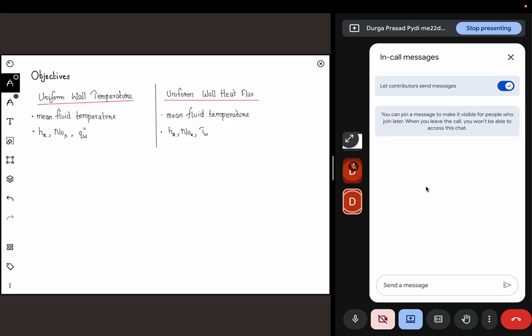So if I want to do something like that, I need to have a process where temperature remains constant. Which process will have constant temperature? Phase change. Phase change is a constant temperature process. So all I have to do is, whichever way I'm doing the experiment, connect the external wall to a material which is undergoing phase change. Then it will continuously take heat without changing the temperature of that surface. So whenever that phase change is happening, that particular wall can be considered as a uniform wall temperature.